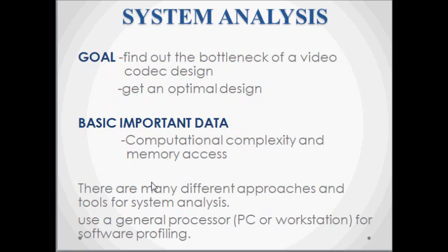Before hardware architecture design, system analysis is the most important step to have insight into the design problem designers face. The goal of system analysis is to find out the bottleneck of a video codec design so that designers can focus on it and get an optimal design. The basic data that we want to get from system analysis are computational complexity and memory access.